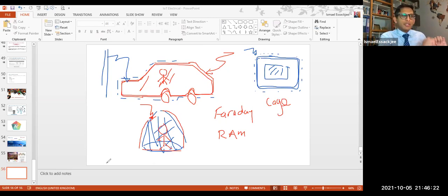We just need to calculate the load, what we call the design current, and then check the protection. Is it a fuse, a circuit breaker, whatever you are using? Do the voltage drop calculation, and then check the loop. In case we have a fault, remember we discussed RCD and so on. We just need to calculate the fault loop impedance, and so on.